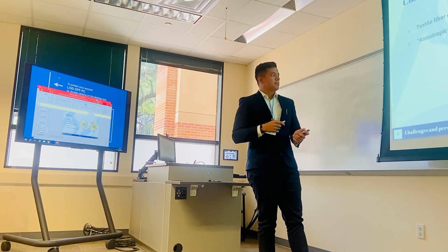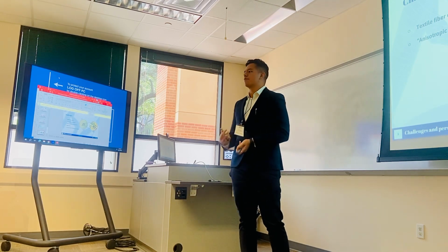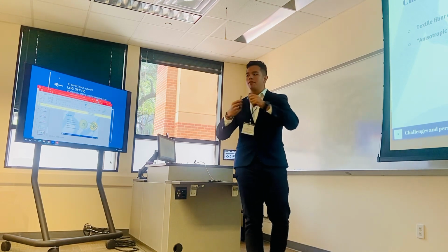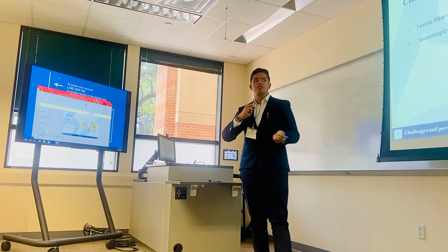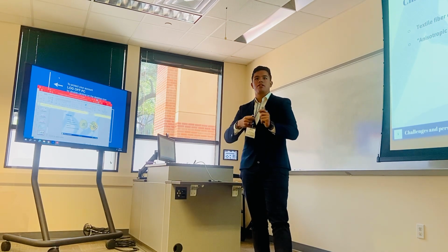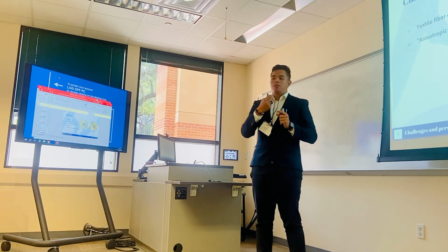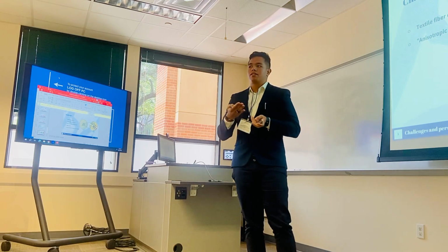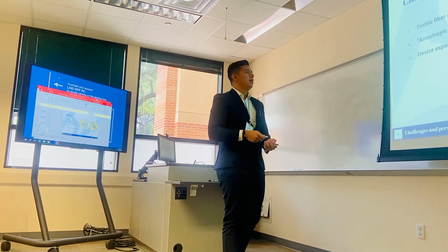And we actually observed something we dubbed anisotropic conductivity. We tried to find some term for it in the literature, but we couldn't find anything related to this, because the conductivity of the device behaved differently depending on the direction you twisted it. So it was conductive in one direction, but in the other it wasn't. That's why it was shown for only two behaviors, twisting and bending, because in the other ones we did not see any conductivity because of the morphology of the fibers themselves.